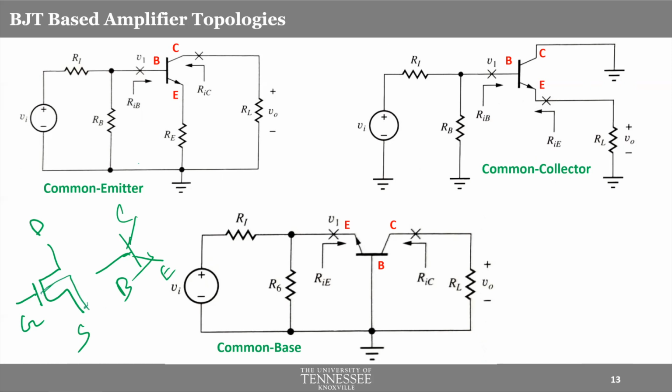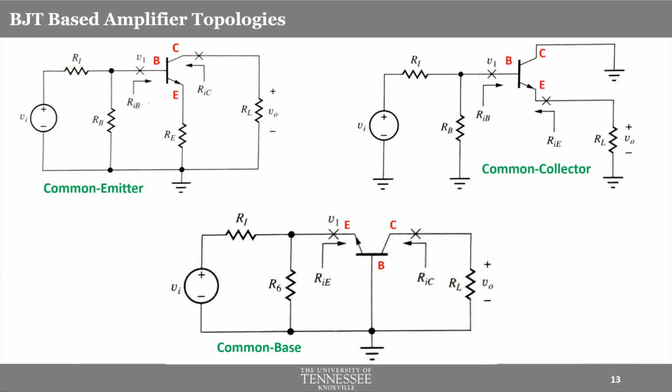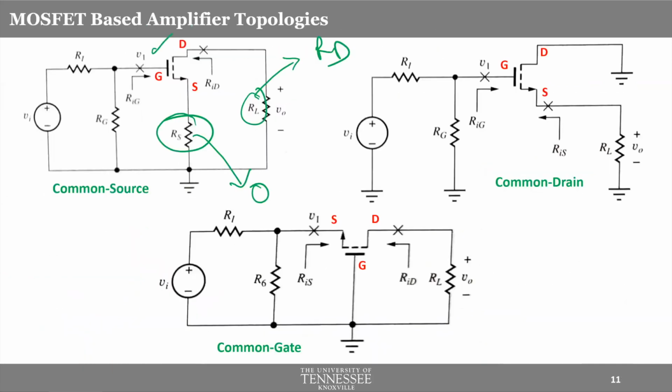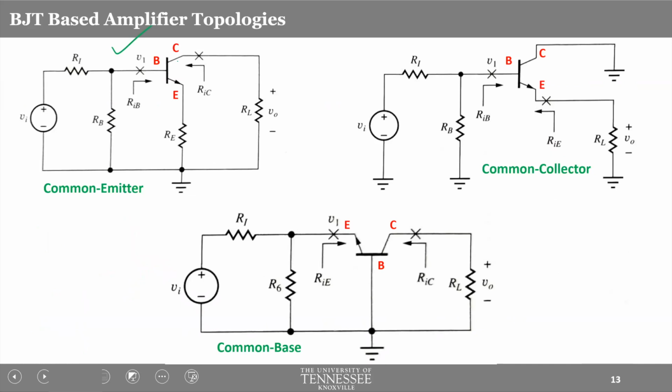Then essentially, you can just replace this MOSFET with a BJT, and then instead of drain, you can call it collector. Gate, you could call base. Source, you can replace with, say, emitter, right? And that's what you see here in this particular circuit. Just compare that with whatever we had here before. It's as if we have just taken this transistor and replaced it with a 3-terminal BJT. That's it. Nothing else changed.